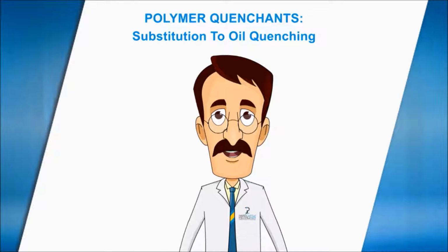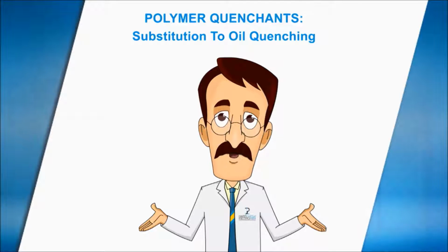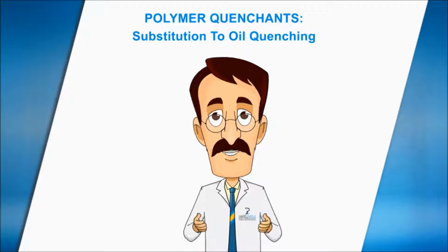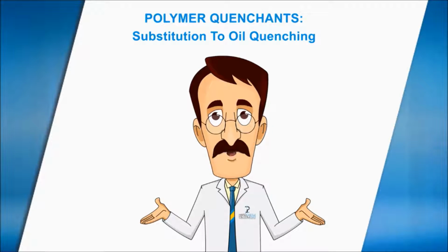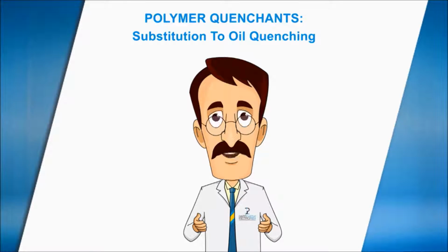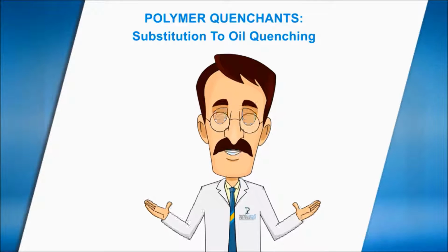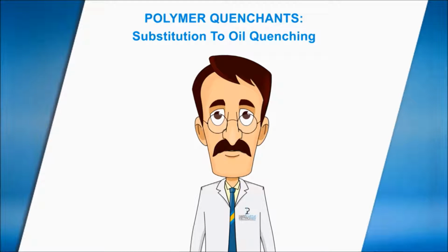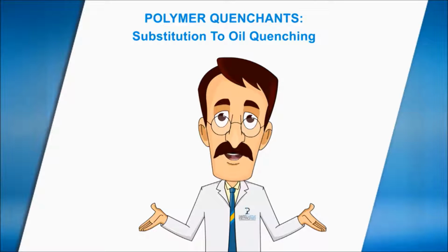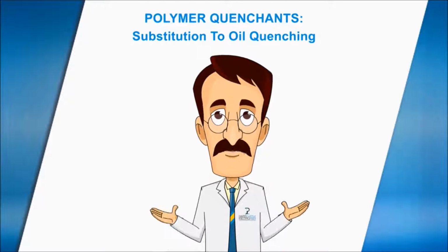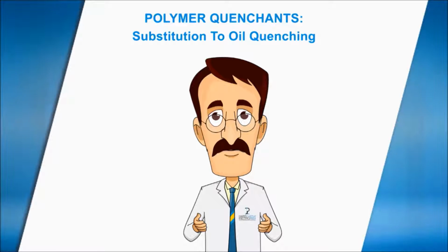As a result of our continuous development programs, we are today able to offer users a complete range of water-miscible quenchants which successfully covers the whole spectrum from oil to water quenching. Accelerated quenching oils can already be replaced in a wide range of applications, as polymer solutions are available which give comparable cooling characteristics. These solutions are therefore suitable for hardening alloyed quench and tempering steels and some tool steels, as well as for quenching components directly from forging.